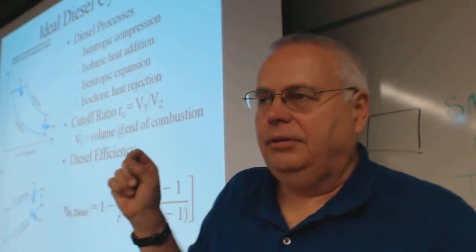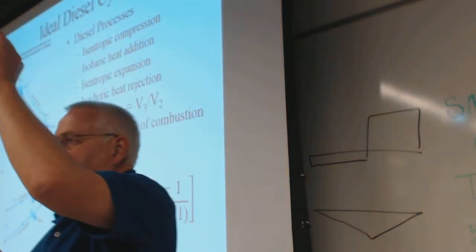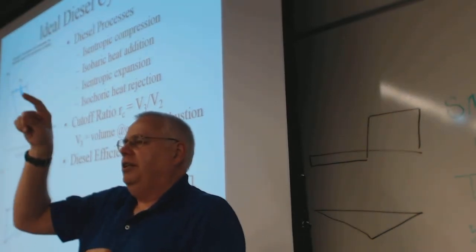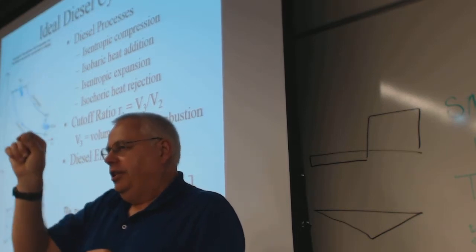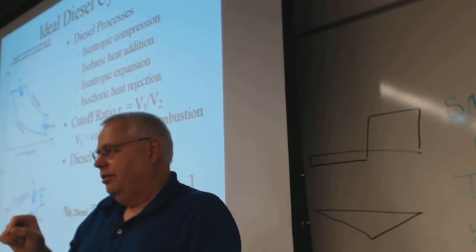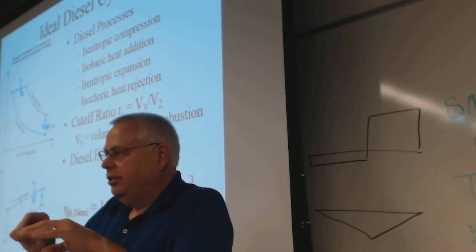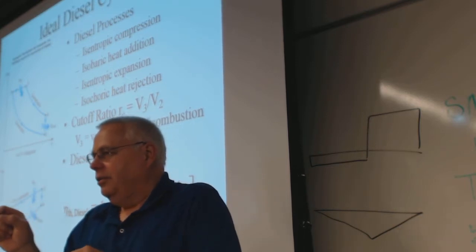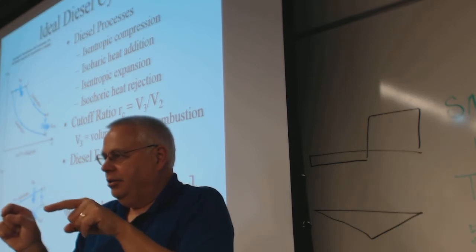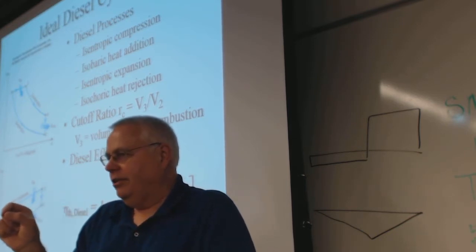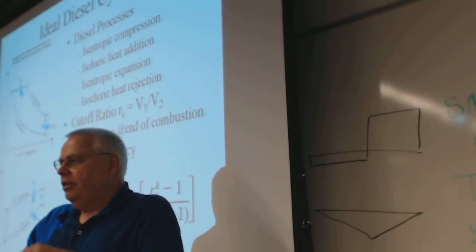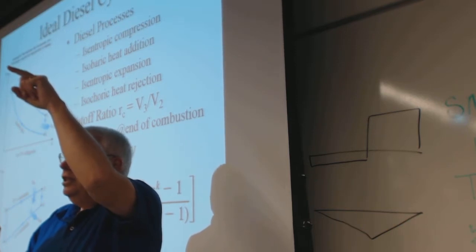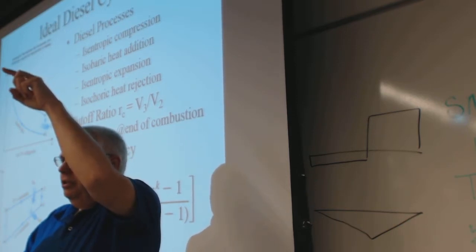If you have a steam turbine and it starts off at some high value of enthalpy, there's a corresponding entropy value for it. The most energy it has available to convert will be a value at the new pressure that has the same value of entropy. If you can find where on that pressure, in the saturation zone, that has the same value of entropy, then you can find the value for H there, and that's the maximum amount that's available to be converted. The real turbine might only convert 90% of that.